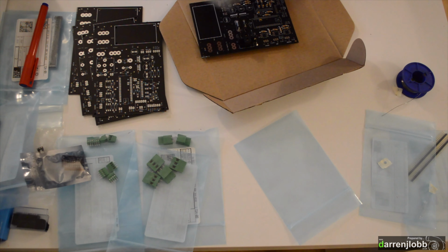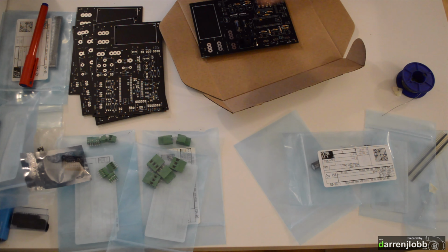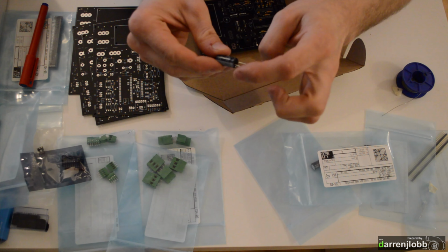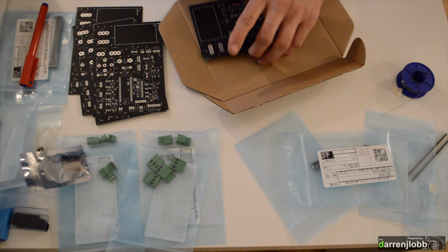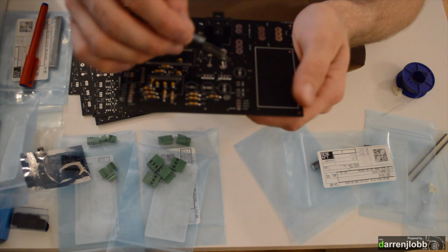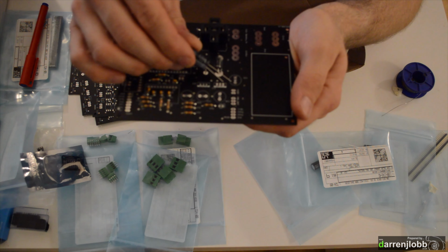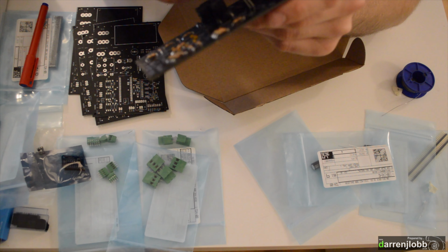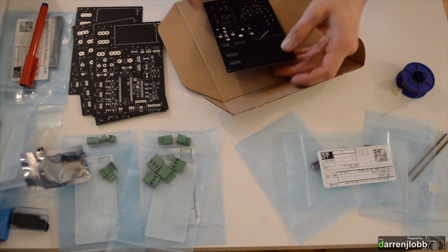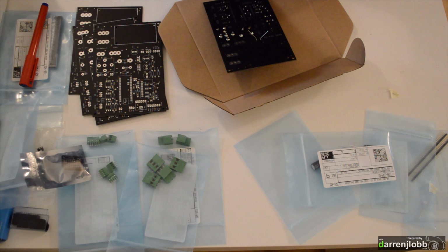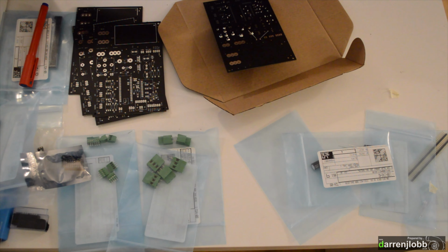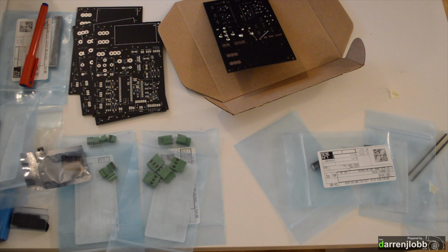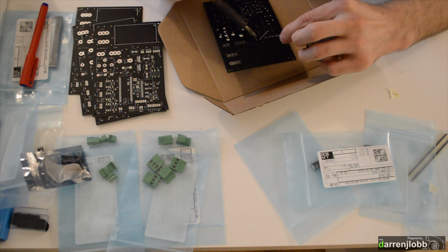So now we'll move on to these larger 1000 microfarad caps. Again, you've got the white stripe and the shorter leg, that's your negative side. And I should have said, you can see on the board the plus sign is marked and also the negative is the white line, so you can't really go too far wrong there. You want to try and keep the bigger caps down as tight on the board as you can. I find if they're not, you'll end up damaging them if they can move around, which you don't want.